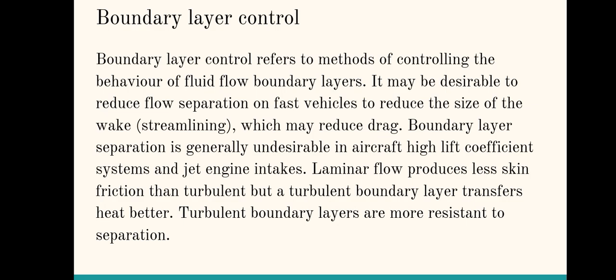So, boundary layer control. Here we can discuss boundary layer control, which refers to methods of controlling the behavior of fluid flow boundary layers. It may be desirable to reduce flow separation on fast vehicles to reduce the size of the wake, streamlining, which may reduce drag. Boundary layer separation is generally undesirable in aircraft, high lift coefficient systems, and jet engine intakes. Laminar flow produces less skin friction than turbulent, but a turbulent boundary layer transfers heat better. Turbulent boundary layers are more resistant to separation.